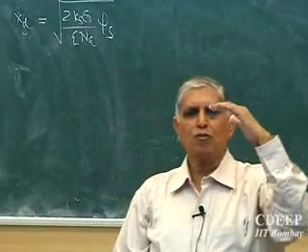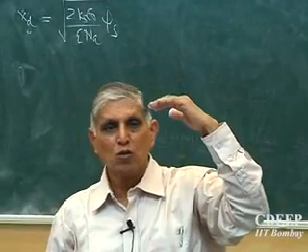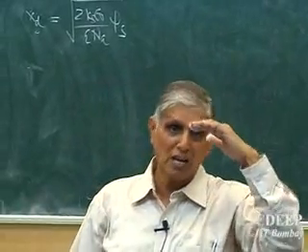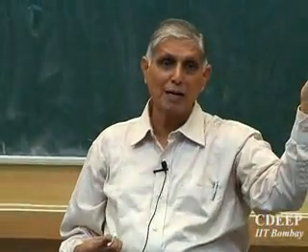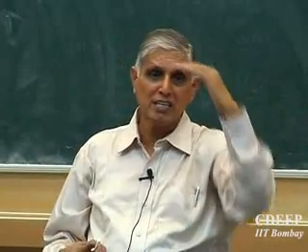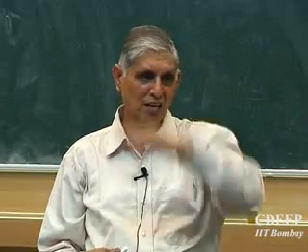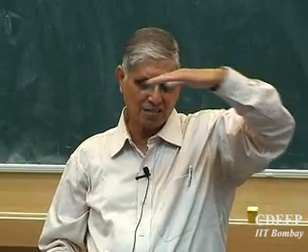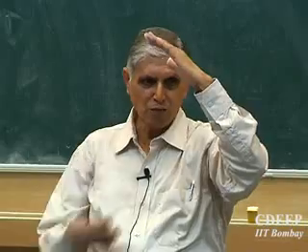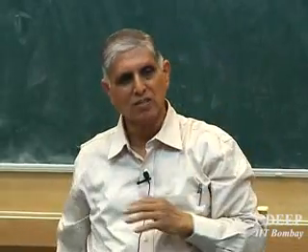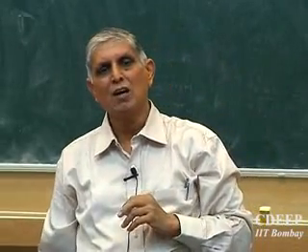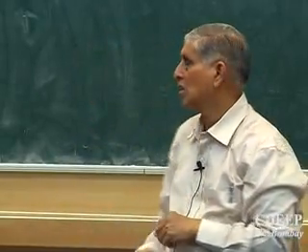It is the potential from VGS equal to 0 to the potential of Ei bending when the applied bias is applied. The band bending of Ei is essentially called the surface potential. Is that clear? The Ei was flat earlier. As you apply bias, it went down. So how much it went down is called the band bending or the surface potential.